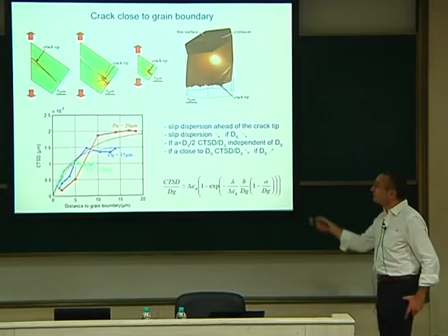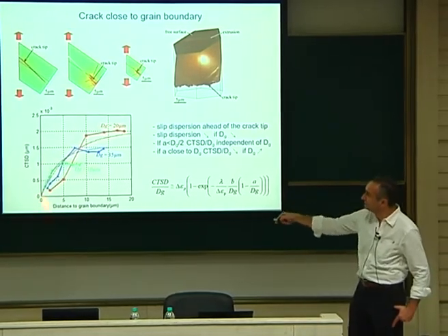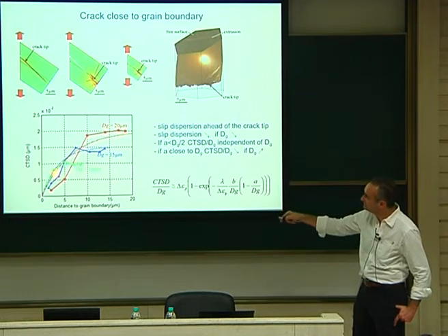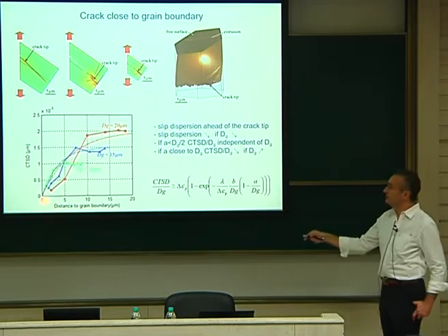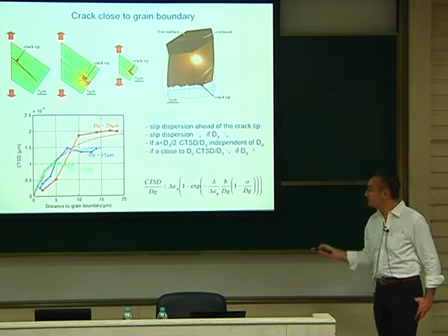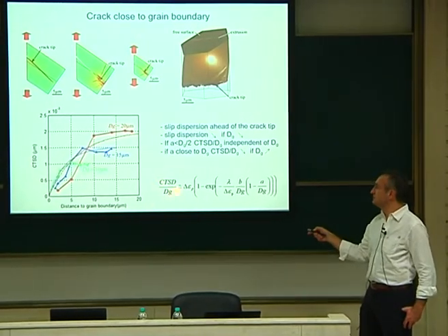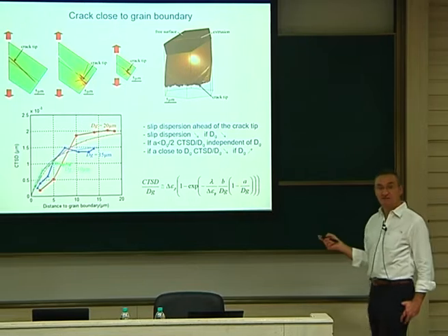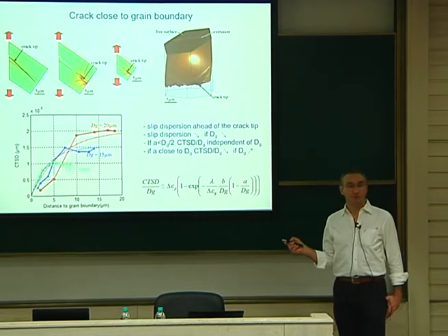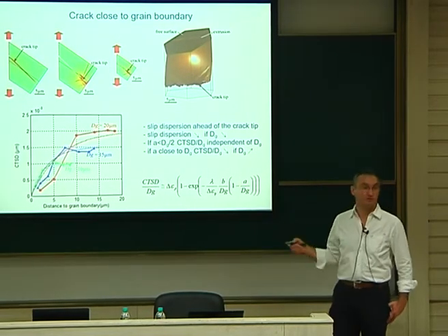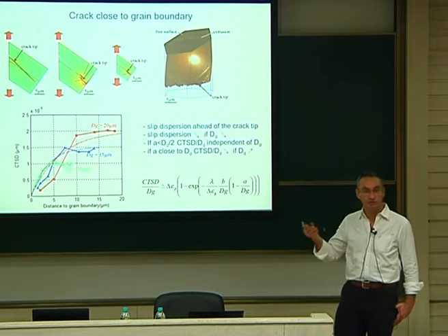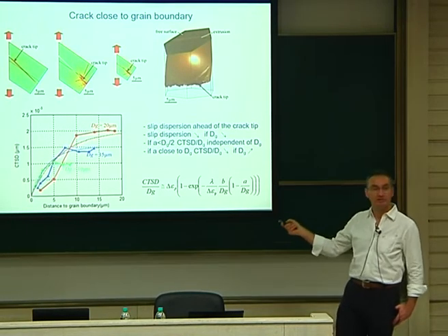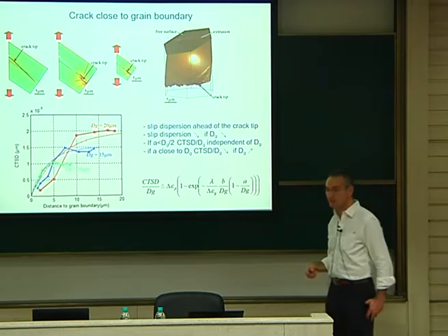Okay? And from that we were able to fit that kind of curve here, which depends on the diameter. The fitting curves are the dotted lines here, like this and like that. And if you fit that with exponential laws, it looks like this. You have the crack tip slip displacement versus the diameter of the grain, which follows such a law. This is nice for people from damage mechanics, because this is typically the crack advance. Here we have the crack advance, so you know the dA over dN that people are plotting in log terms. This is exactly what they are looking for. And here we found something which is an exponential term.